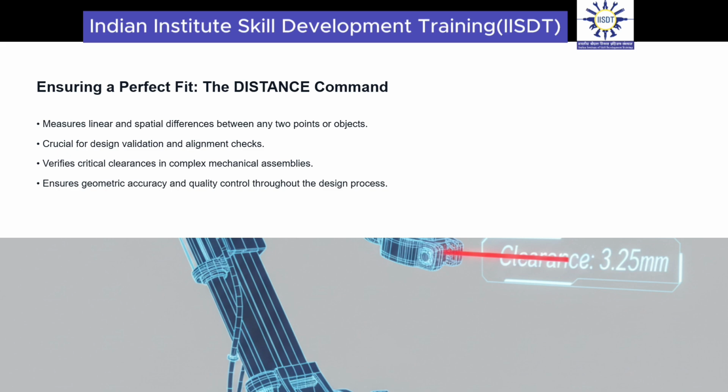This isn't just about finding the length of a single line. The distance command can determine the shortest distance between two complex curves, the clearance between two parallel surfaces, the angle between non-parallel lines, or the x, y, and z coordinates of any point. Its primary role is in validation and verification.